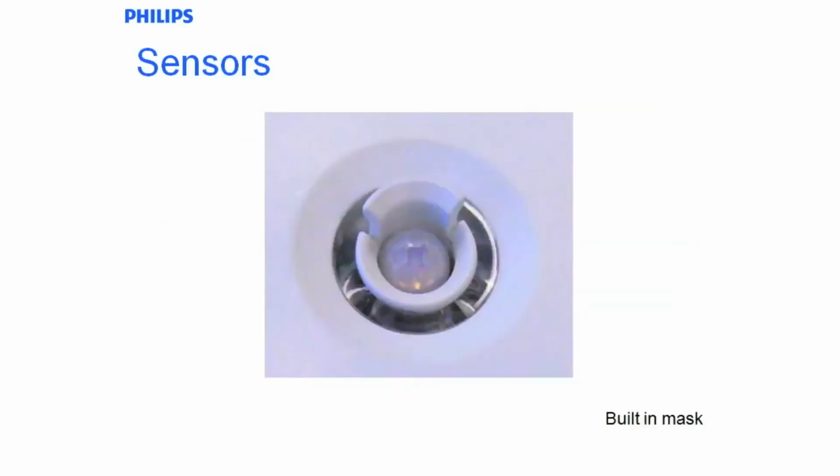This sensor also has an integrated motion shield. So if you have a doorway close by that you want to shield away from occupancy sense, you can rotate the sensor around as part of the installation and drop the shield to make sure that you have a blind spot, so not to pick up passing traffic. This is a very, very useful function.